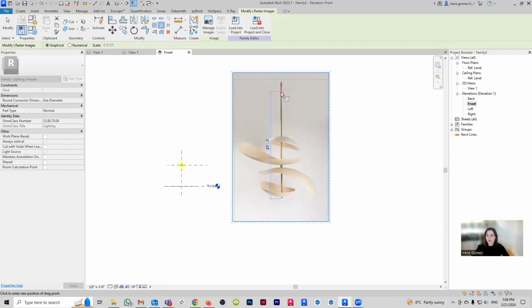One of the things that I really like about Revit is that Revit is a unit-based software. That basically just means that it doesn't matter what unit system I choose. Whenever I type a value, as long as I indicate the unit as a suffix, Revit will automatically scale and adjust those dimensions for me. So even though I'm working with Imperial, I can type 75 because all I need to do to make sure that Revit is scaling correctly is type CM at the end.